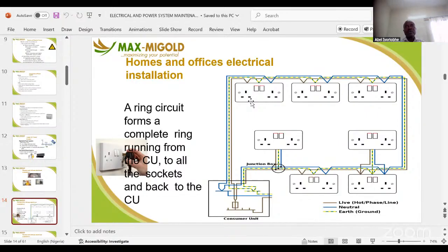So if a cable is overloaded, it will lead to fire as well. It will heat up and melt together. If you are not there to quench the fire, it's a big problem for the building. So people now disuse the ring circuit form of installation, but developers still make use of ring circuit installation because they want to save cost. The cost of ring is cheaper than the cost of radial, which is the other one.